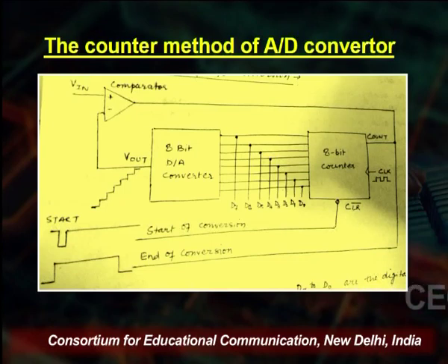So, basically the op amp in open loop configuration is being used as a comparator. It is comparing both its inputs and seeing whether it needs to change from plus saturation to negative saturation or vice versa. This comparator is used as a control signal in this circuit.